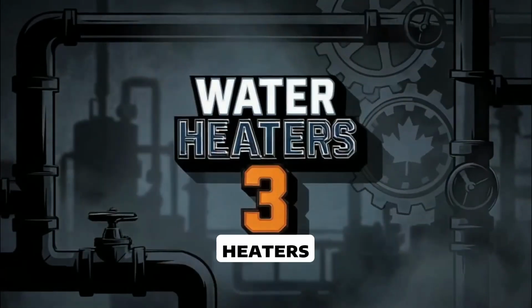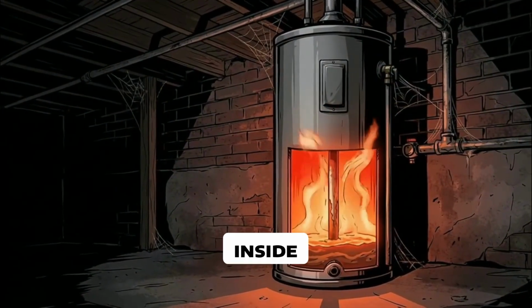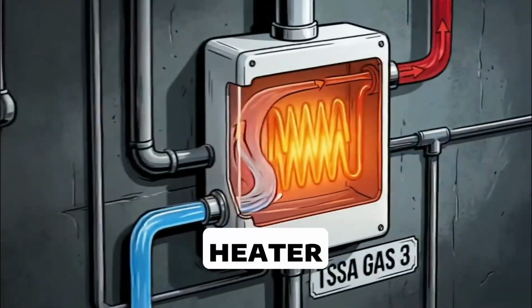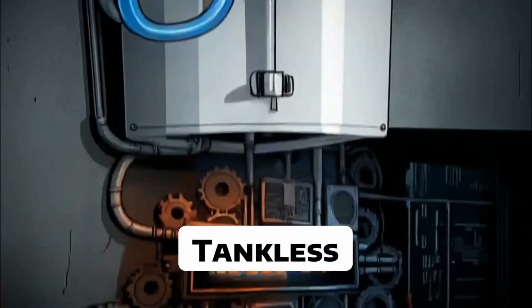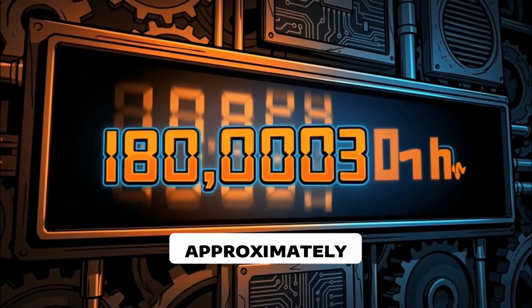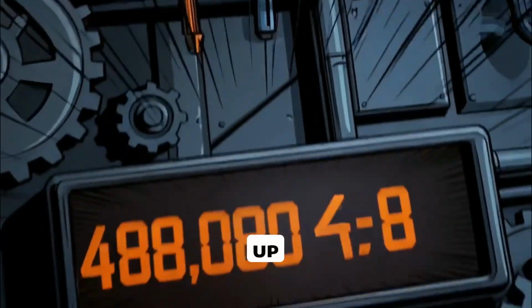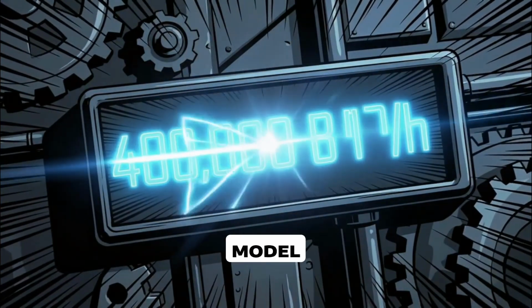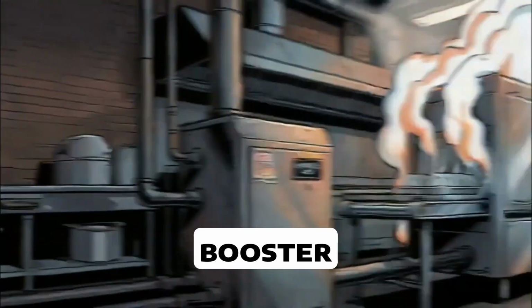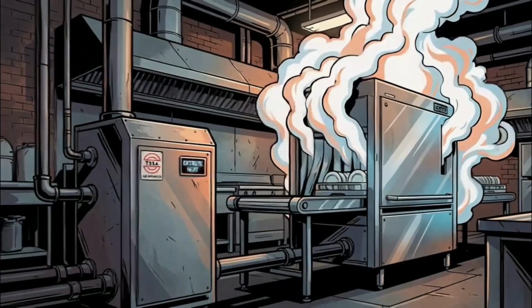Now, water heaters. There are three major types. A storage tank water heater stores hot water inside a tank. A tankless heater heats water instantly when water flow begins. Tankless units may have inputs from approximately 180,000 British thermal units per hour up to 400,000 British thermal units per hour, depending on model and application. A booster heater raises water temperature higher, often for commercial dishwashing.